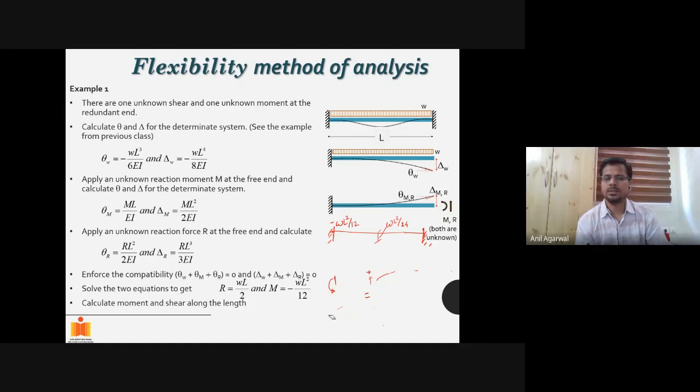Okay, and if that is the case, this is not a very efficient way of designing it, because this beam has a very high negative moment demand, in comparison to positive moment demand. So what I can do is I can take the average of the two. How much will be the average of the two? Or WL square by 16, right? Agreed? So if my beam's negative moment capacity is only WL square by 16, and I'm sure that it has